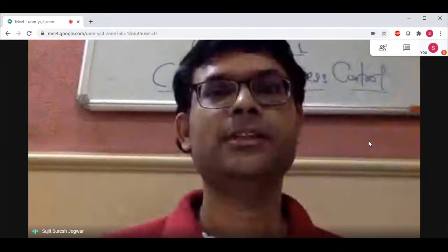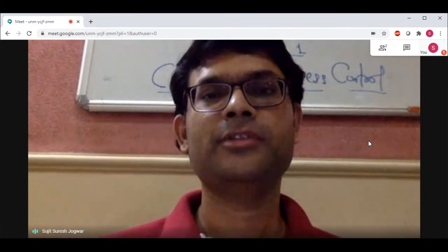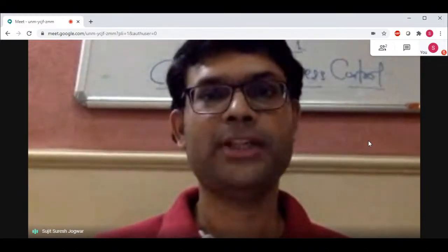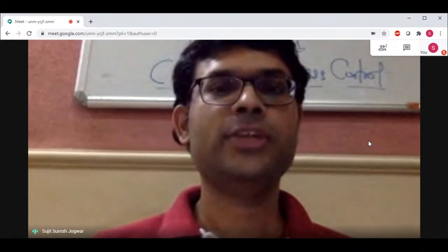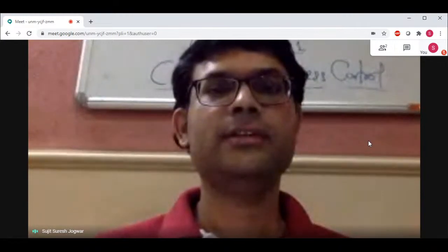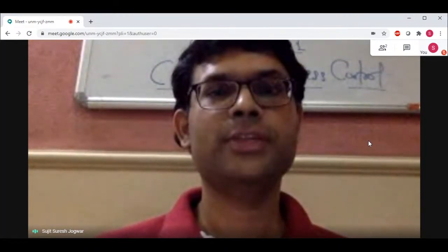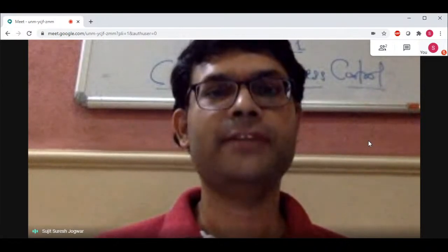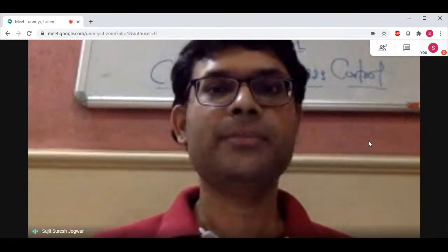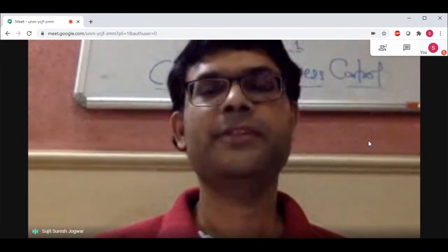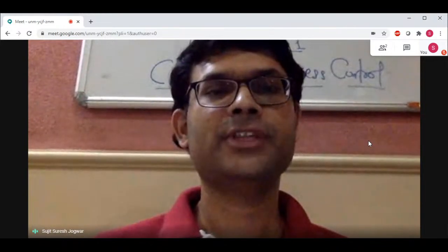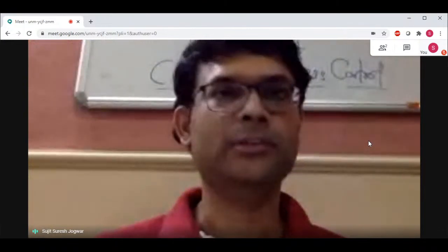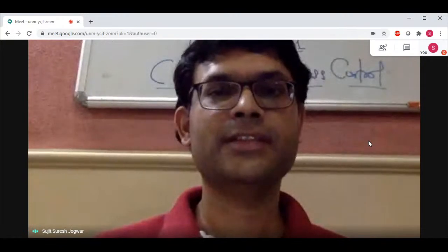constant, then we have seen through mathematical derivation that the response of the system is given by A Kp times (1 minus e raised to minus t over tau). So in order for this system to reach A Kp, e raised to minus t over tau has to go to 0, and that will go to 0 around when t is equal to 5 tau. So that is why typically we say that if it's a first order system, it takes 5 times the time constant to reach the steady state. A lot of times we also take the 95% response, which comes at around 3 tau also. So these are just rough estimates.